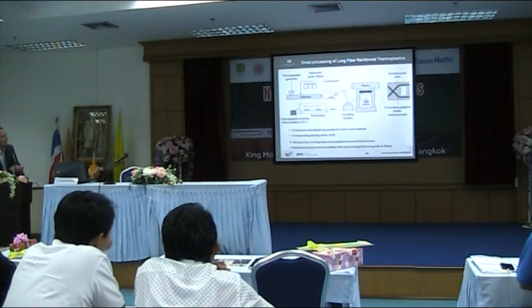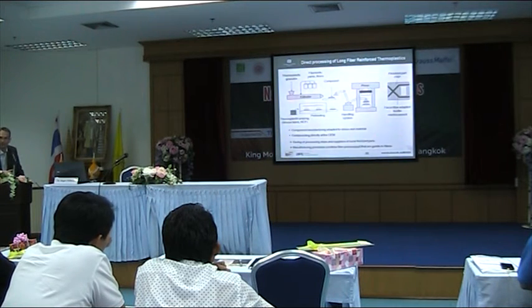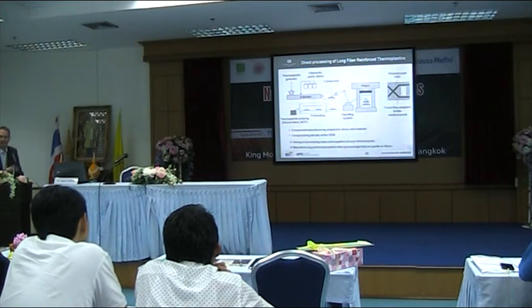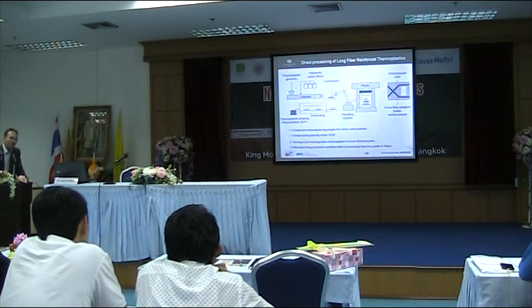So we have some endless fibers here, but additionally you can add some compound from a classical compounding process, extrusion process. You have some compound here, and you can combine it together in a press with a compression process, and you get a fiber reinforced part with chopped fibers, fiber lengths of 5 millimeters up to 10 millimeters, but with an additional local reinforcement with endless fibers.